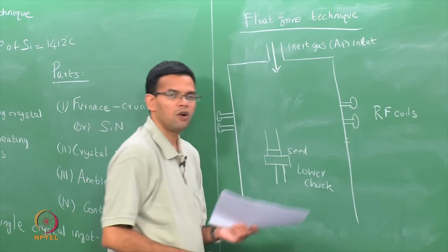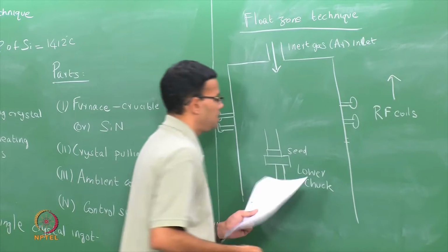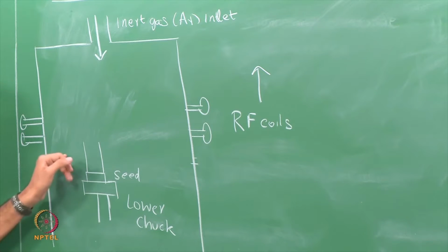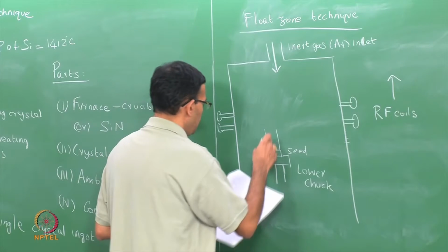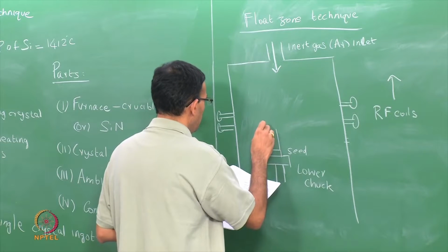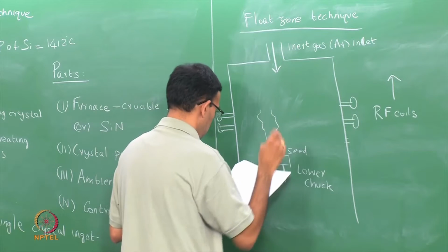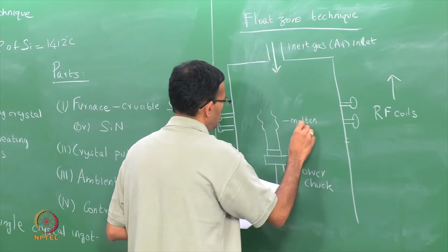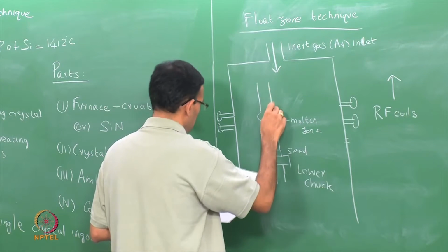So, these RF coils are used for localized heating and melting, and they travel along the length of the furnace. They are basically wrapped around the silicon ingot, that is from your electronic grade silicon, and as it goes, it melts the silicon in order to create a molten zone. The molten zone. Then there is the rest of the ingot that is on top.